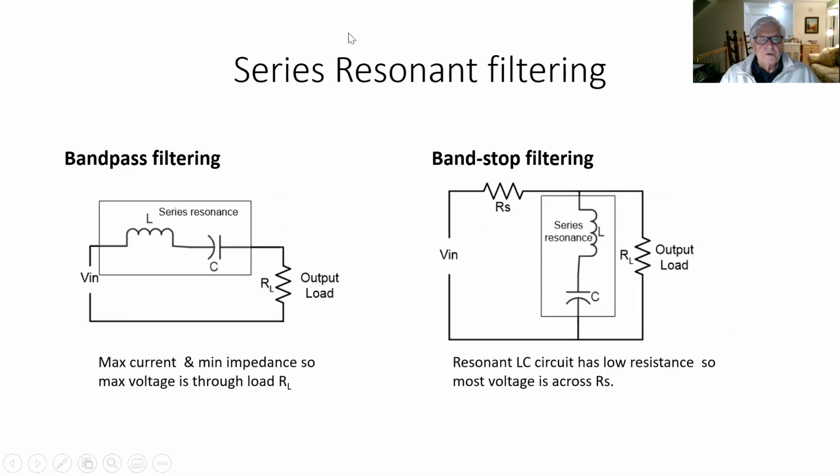So we can use series resonant filtering, where we take the output across the resistor and our resonance is through the series LC.